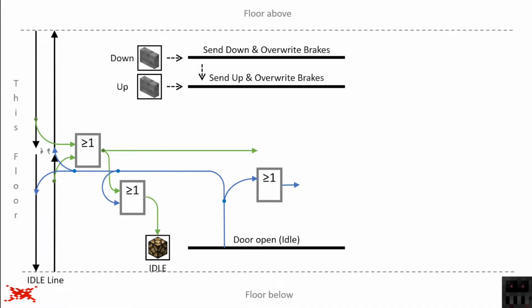Now let's say I want to make a call. Well, as I already said, all I need to do is press the button since I'm reusing them for making a call. So I have some kind of delay due to the internal processing times, and buttons are monostable circuits. Subsequently, since I also don't want to deactivate this floor, and if you remember to the last episode, if I were to give a constant signal on either of the send down or send up internal bus, I would deactivate this floor. So subsequently, I have to work with pulses, which is the reason for this monostable circuit there.